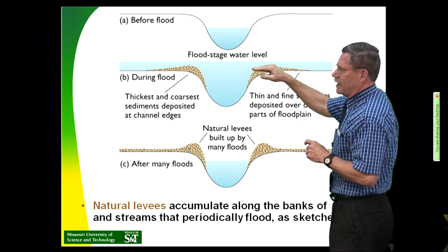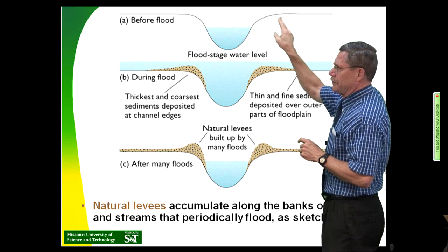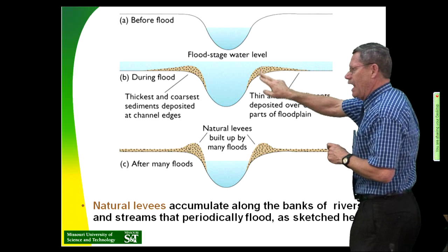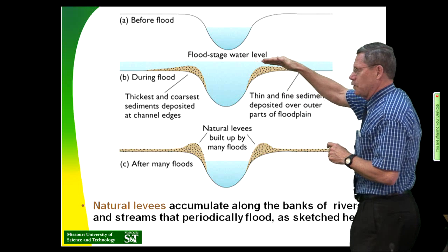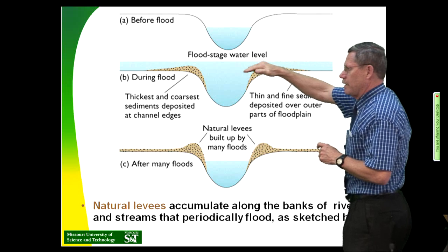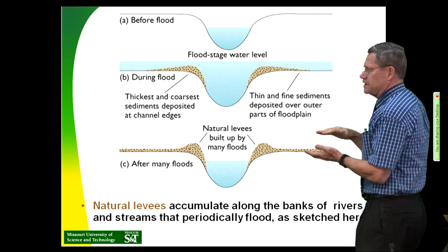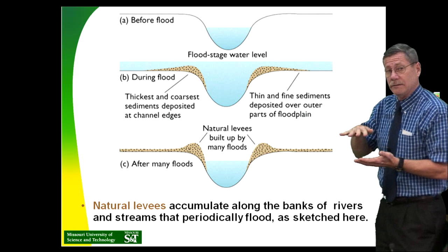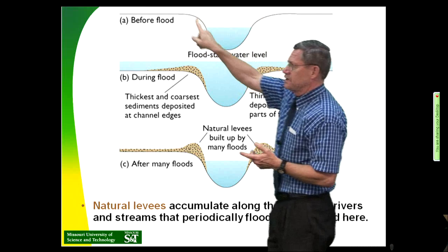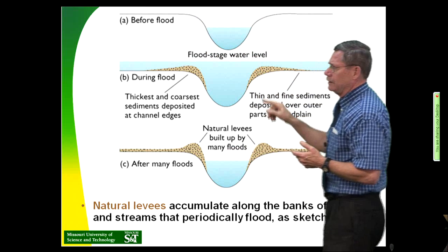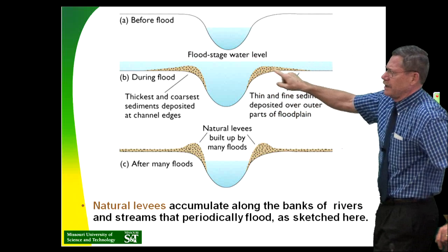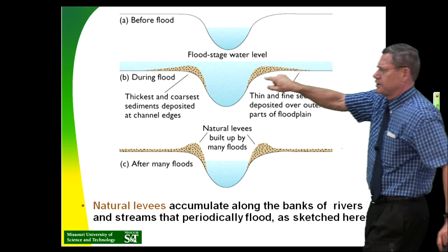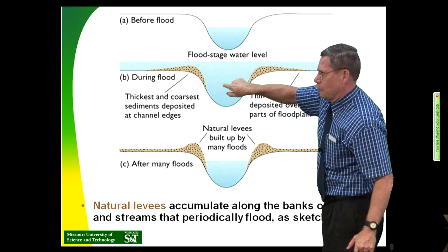But as soon as it gets up to the top here and spills over this lip right here, what's going to happen on this spillover is you have a lot higher roughness, and you only have like 1 inch of water when this thing starts to come over. So your ratio between Q and roughness is suddenly one or 2 orders of magnitude greater than it is out here in the slicker than snot on a doorknob channel. And so what happens is the sediment, suspended load, starts dropping out because velocity drops dramatically going in this direction as compared to going straight down the channel.